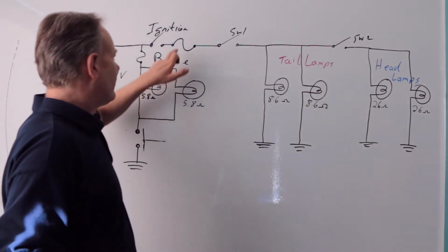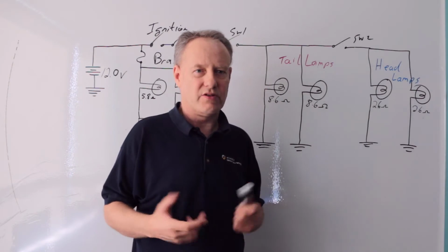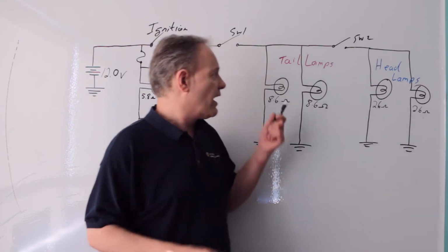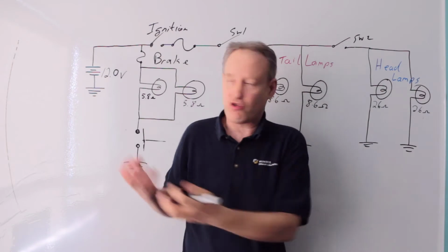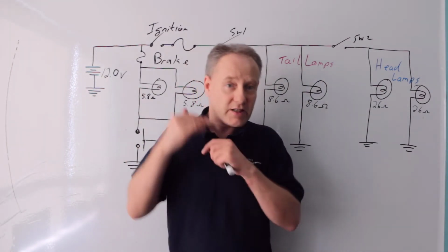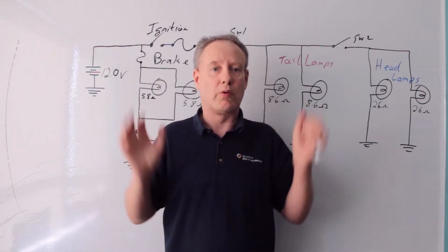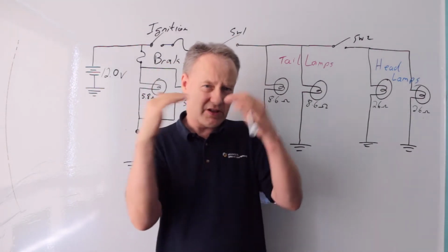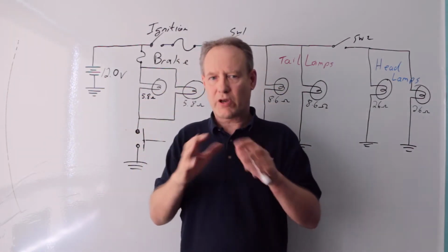Okay, good. So how do I calculate the size of these fuses? Well, what I do is, I do the math, use Ohm's law, and maybe some resistance calculation formulations for parallel circuits, and I find out how much these are drawing. So how much are these loads drawing from that battery? And then I want to make sure that I put a fuse in there that's more than what they're drawing. If they were drawing exactly 10 amps and I put a 10 amp fuse in, boom, it would blow right away. I want to put a fuse that's in between 15% over and 35% over. So kind of aim for the middle there, but you're not always going to get exactly in the middle. So it's okay, we'll go through that process.